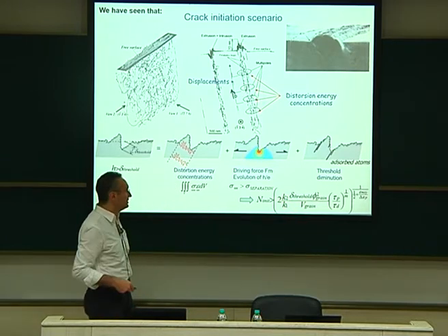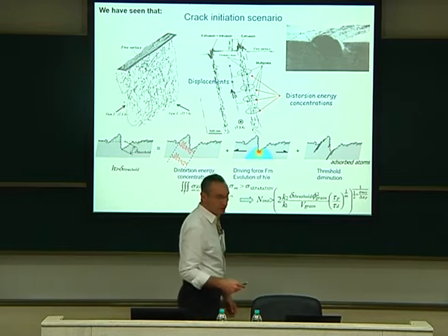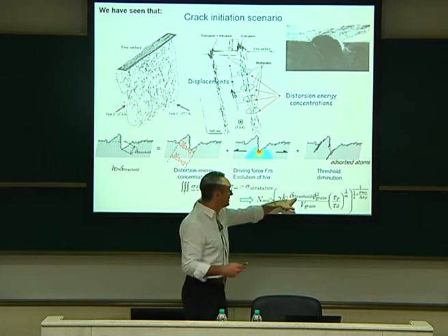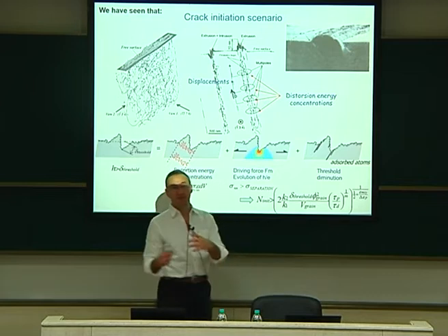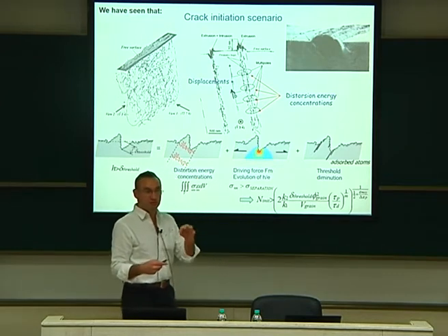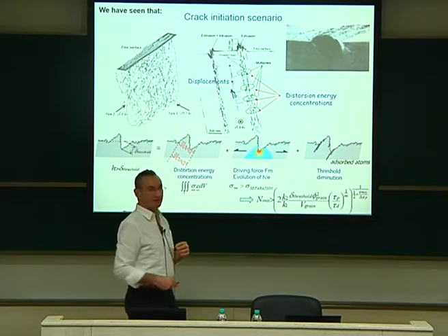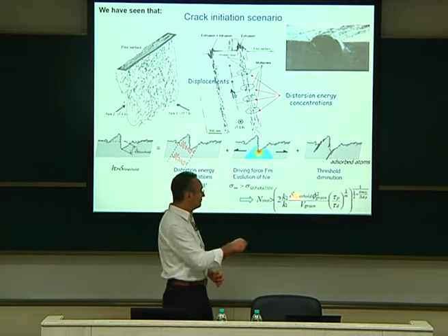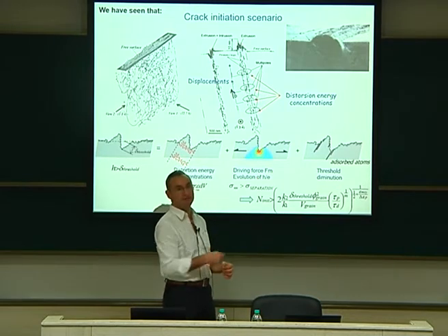So you have many parameters that enter into play in the model. It means that now we know how it depends on them. We don't know exactly the threshold, because this depends on your material and many parameters. So if you want to use that relationship, you just need to measure one point experimentally that will fix this threshold, and then you have your dependency.